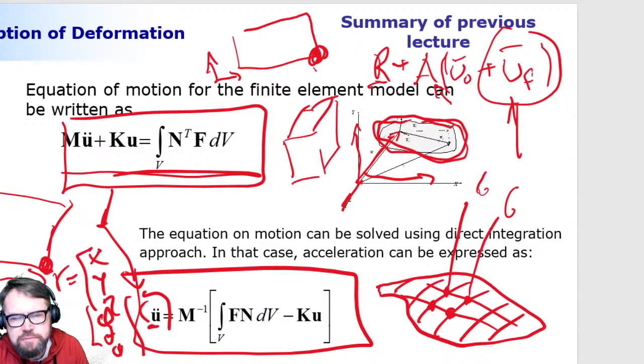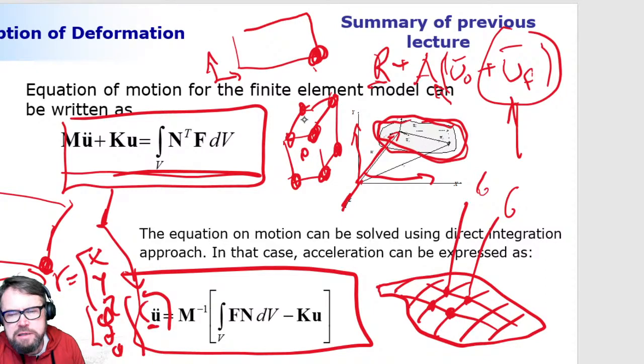They typically have 3 degrees of freedom per nodal location. And these are just the displacement, nothing else. So this would be the element with 8 nodes, and each one of the nodes would have 3 degrees of freedom. But again, it really depends on what kind of element you decided to use.